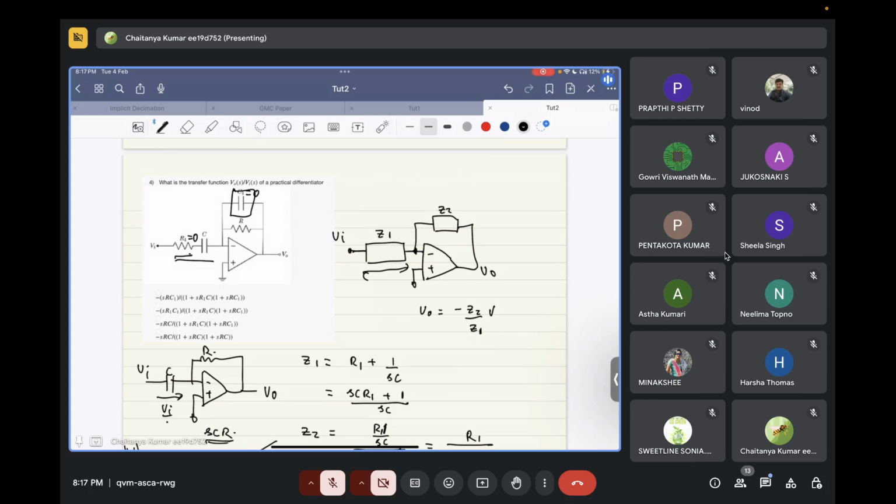So basically, what happens is, this parallel plate capacitor will have some wire with which you will connect it to, let's say, a PCB, right? So that wire will have some series resistance, and there will be some resistance in series with this resistor. For example, this resistor is made something like this. Now there will be some capacitance that will form between the soldering ends of the resistor. So that will act as some parallel capacitance along with the resistance. So these are some practical non-idealities that exist in the components that you have.